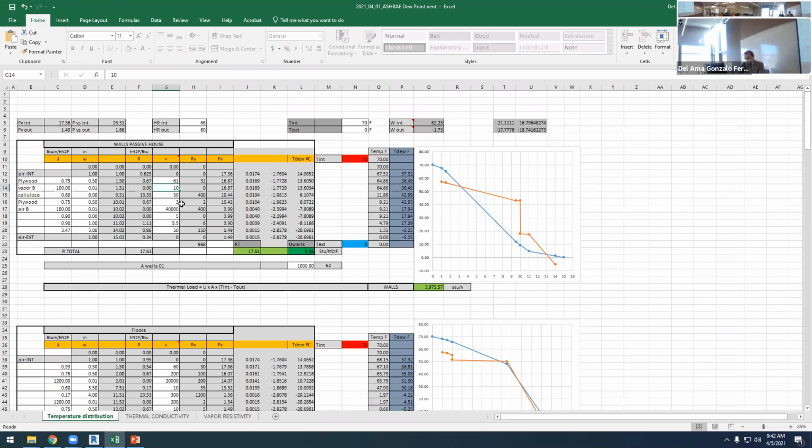Look, I use two different values. We can have 400 and 4 million. If there is 400 inside and 4 million outside, we do have condensation risk. If it's the other way around, 4 million and 400, now we don't have this condensation risk. So in my opinion, this option is safer.